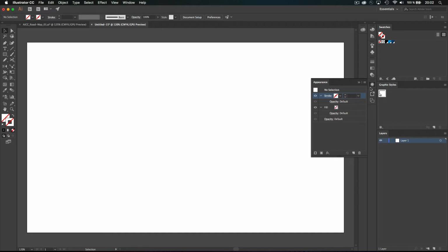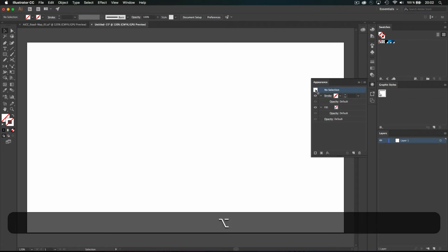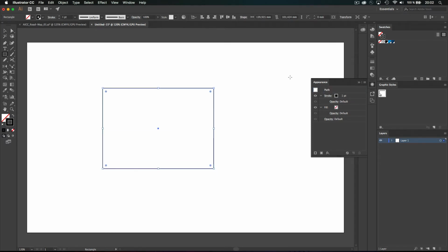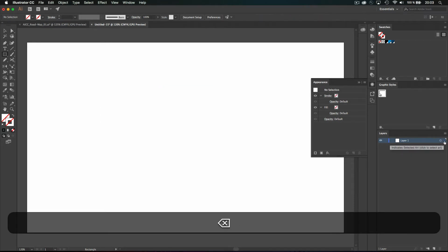And so with that, I will override the default attribute by just dragging with the Alt key on PC, Option key on Mac, and just dragging on top of it. And now that will be my default. So no color. If I have any doubt, because sometimes you grab something, you added some stuff, just press D, and you're sure you have no attribute at this path level, because we don't want to have an attribute and on top of that another attribute that could give you some weird stuff later.